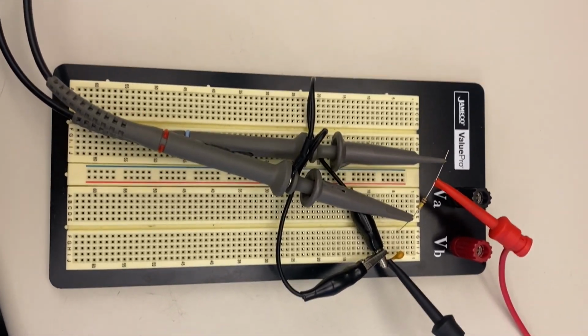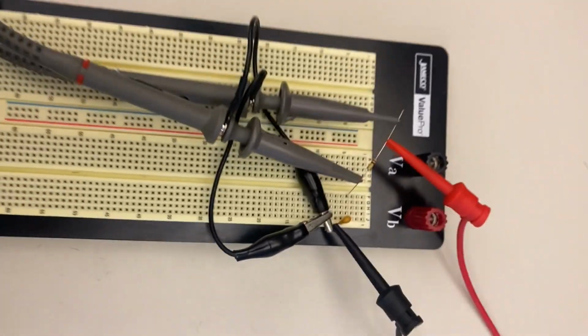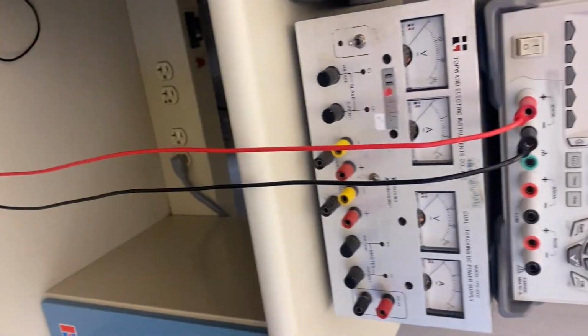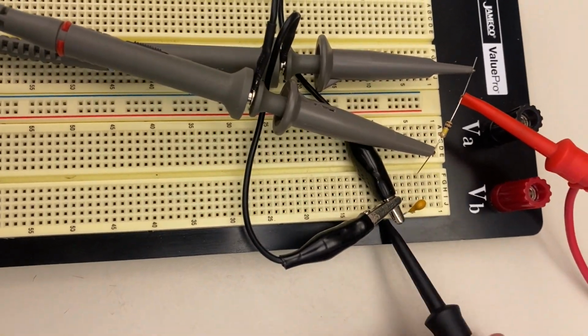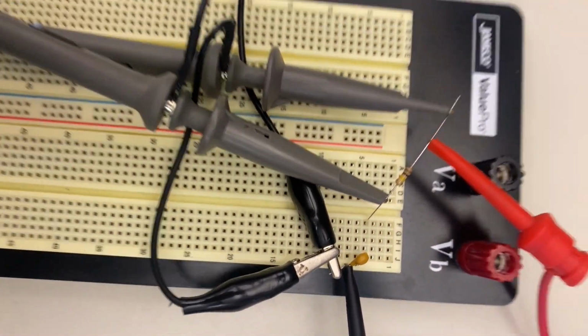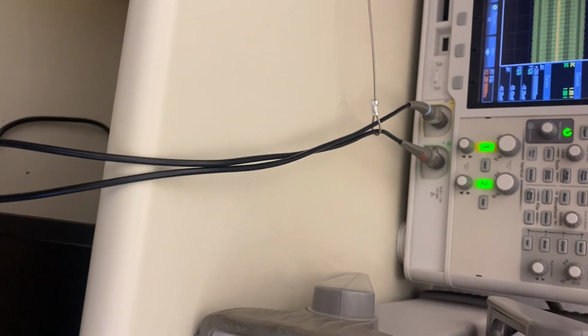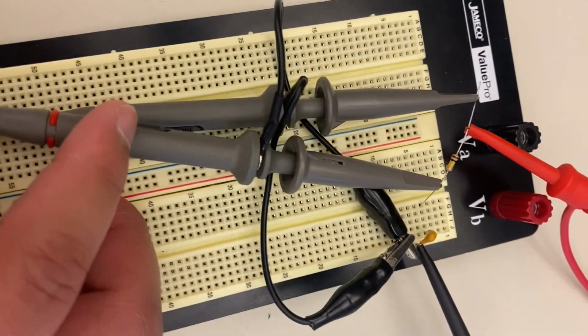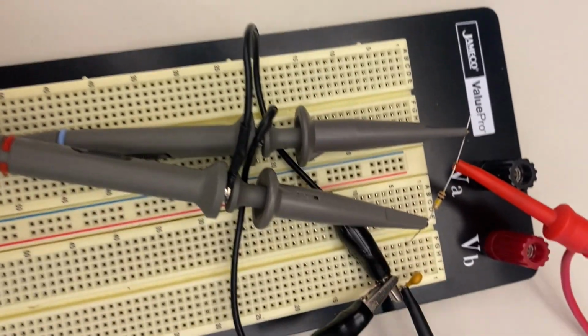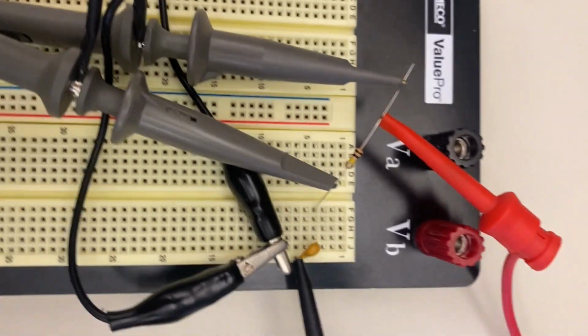In this video I just want to go over how to use the oscilloscope. Right now I've got this RC filter. I've got the power supply coming into the resistor, and then the ground of the power supply tied back to this capacitor, and these are in series. Here on channel 1, this blue wire, I will be probing the input across that resistor and ground, and on channel 2 I'm probing the output, which is this junction between the capacitor and the resistor. So I'm going to go ahead and take a look at the oscilloscope here at the bench.